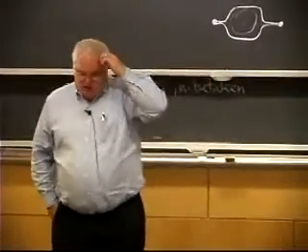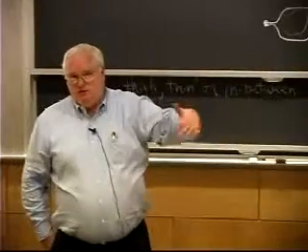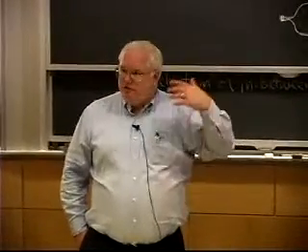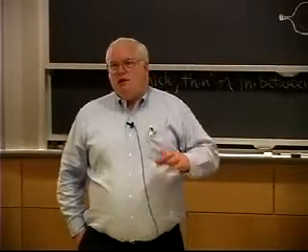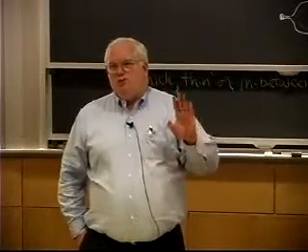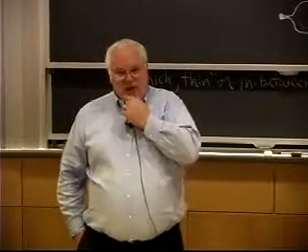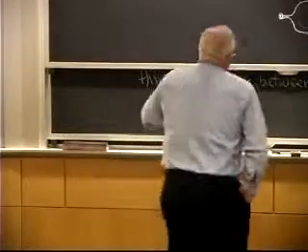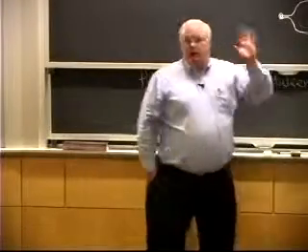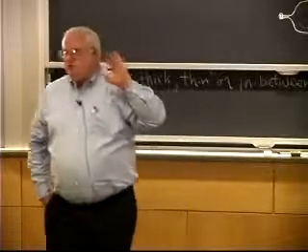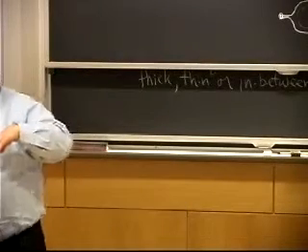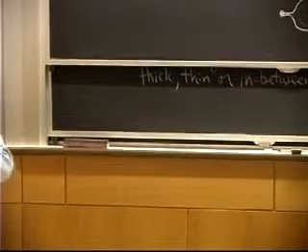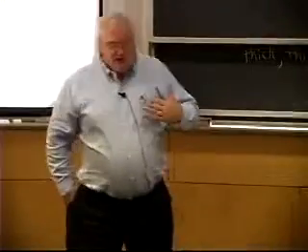And so Bert Schumacher convinced Ford that rather than having, when you're talking automotive production rates, you'd probably have to have 100 of these or 50 of these setups, just welding catalytic converters over and over and over. And he convinced them they could do everything with a much higher speed because of the higher power density without a vacuum electron beam, and they didn't have to bring things into a vacuum. And they could make these welds at 100 inches a minute or whatever, 10 times the productivity rate, only 100 times the increase in cost. Actually, yeah, about 100 times the increase in cost of the equipment. But nonetheless, he convinced them.